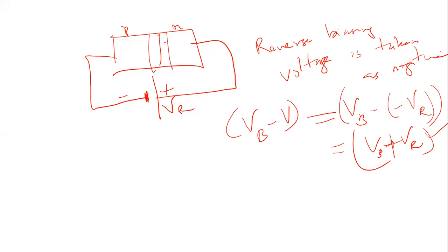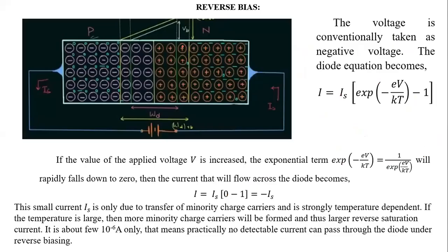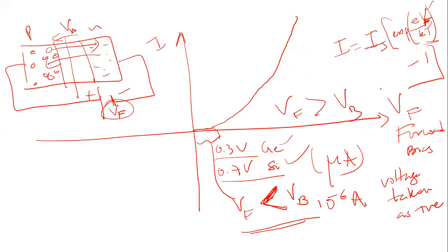If it adds to the barrier potential, if the barrier potential is raised, then the electrons cannot overcome, nor can the holes overcome the PN junction. Then you cannot have any practical current, right? So if you look at this expression here, we put a minus sign here in the case of reverse biasing, like I just said.